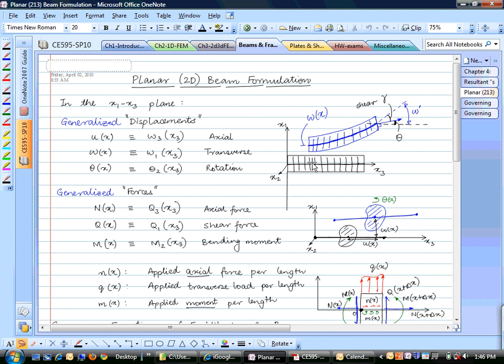And I told you last time that the mathematical model of a beam, you have to visualize it like a centroidal line with lots of rigid cross sections. And when it deforms, it goes to this new position. And here, the angle that the normal vector to the cross section makes... I don't know if you have this figure in front of you in your handout. The normal vector of this cross section might be a little different than the tangent to the centroid.